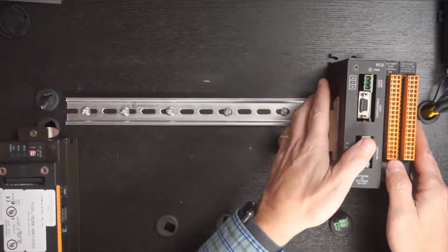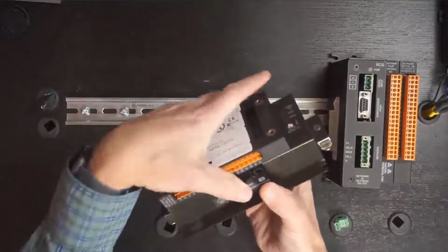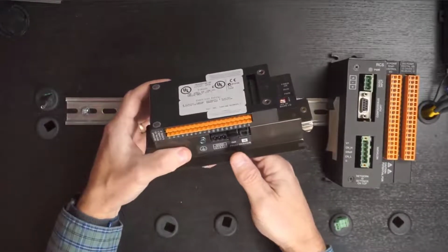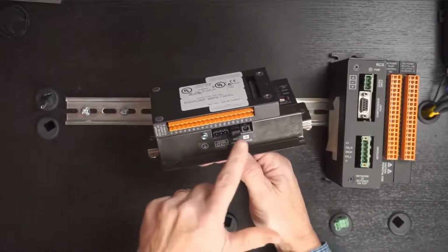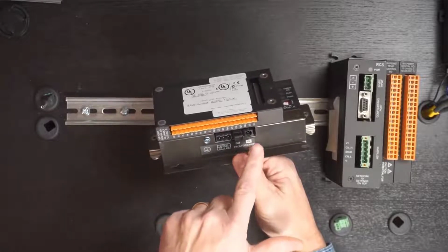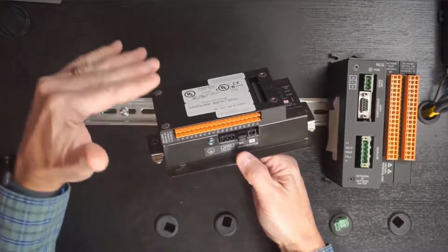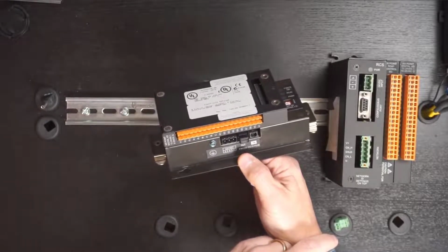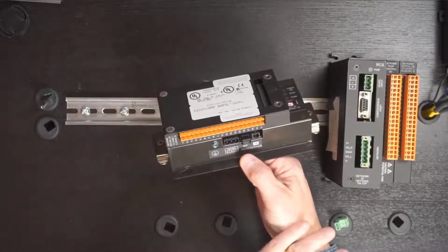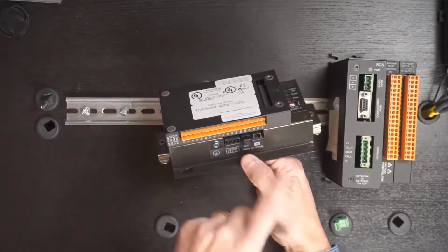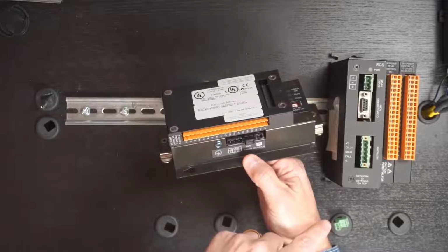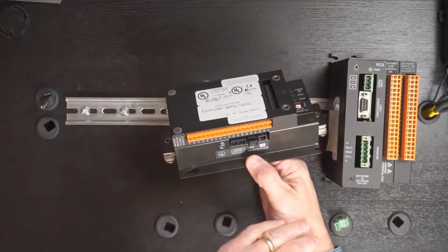And then for a true remote I/O solution, at least from a Smart Stack standpoint, we offered this remote fiber base. Here's one here. It interconnects with Toslink plastic fiber. You can have up to 4 modules plugged on it, and you could have up to 5 of these bases on a system. So you could end up with some fairly large I/O counts, and the maximum distance that any base could be away from the OCS was, I believe, 10 meters maximum.